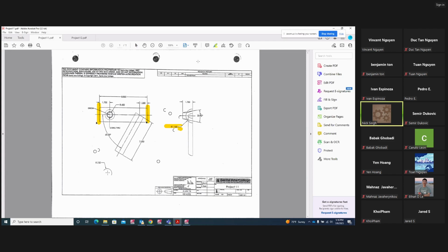And then we're going to draw a line at an angle of 60 degrees on construction plane top, and we're going to create a plane normal to this line right here. Once we create the plane, we're going to create two arcs, radius 750, one arc here, one arc there. This is the radius of the arc. If you look at this, the arc goes right there.